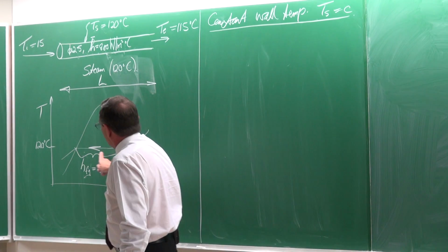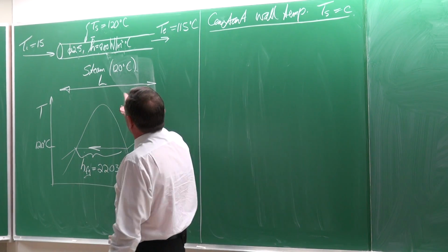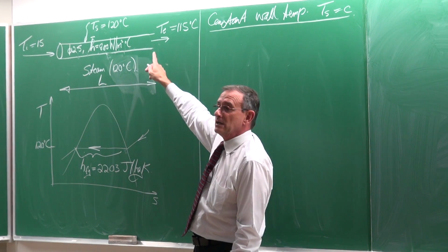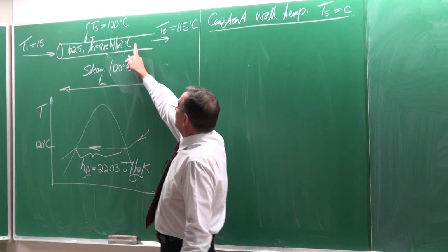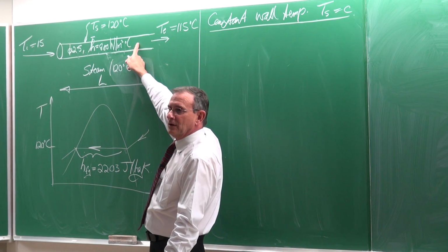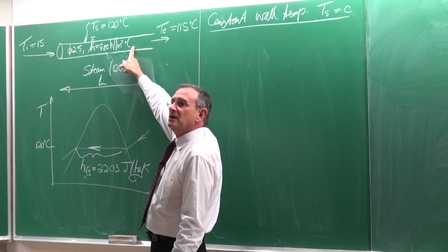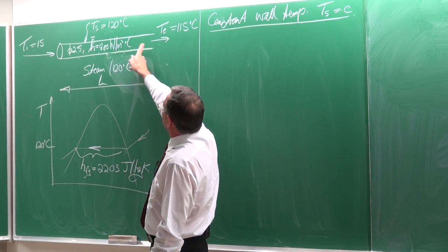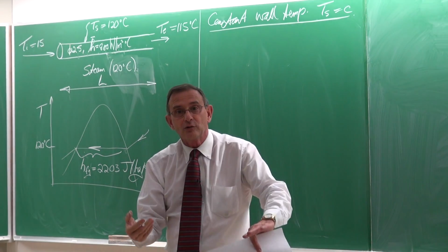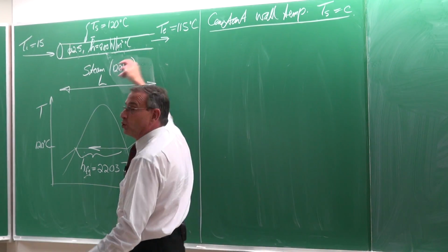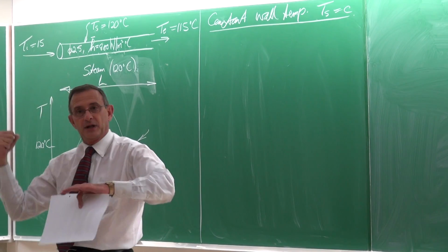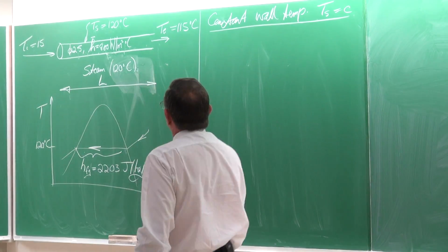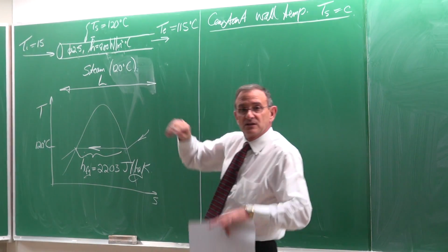Now, although this is going to happen with the steam, the water is going to increase in temperature from 15 to 115. Some of you would say, but now this thing is going to be steam, because it's higher than 100. It depends on the pressure. If the pressure is atmospheric, yes, then that will be the case. But if the pressure of the water is 200 or 300 kilopascals, typically if you pump it through, then it's not going to be steam, it is still going to be water.